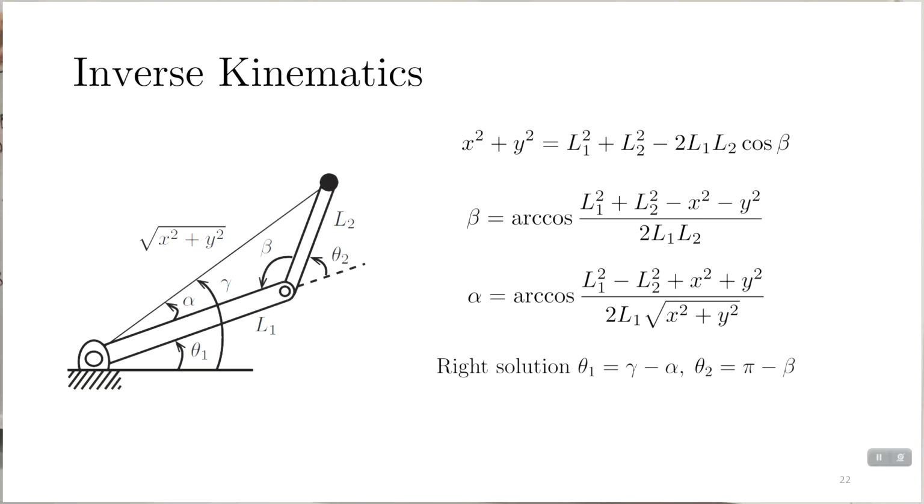So if we go back right here, you know the desired angles. You can measure the actual using position encoders or other kinds of sensors that measure position, and you can compute the error. And then you can use this equation to compute how much torque you need to apply in order to move along this trajectory. Let's have a demo.